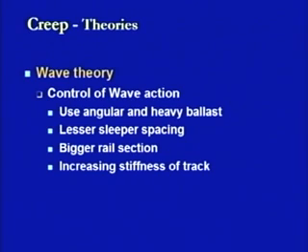Another thing is the lesser sleeper spacing. Just before, I have discussed that if we provide sleepers placed very close to each other, then there will not be any possibility of deformation getting induced because of the load in the rail section. So, this is what we are talking about here.